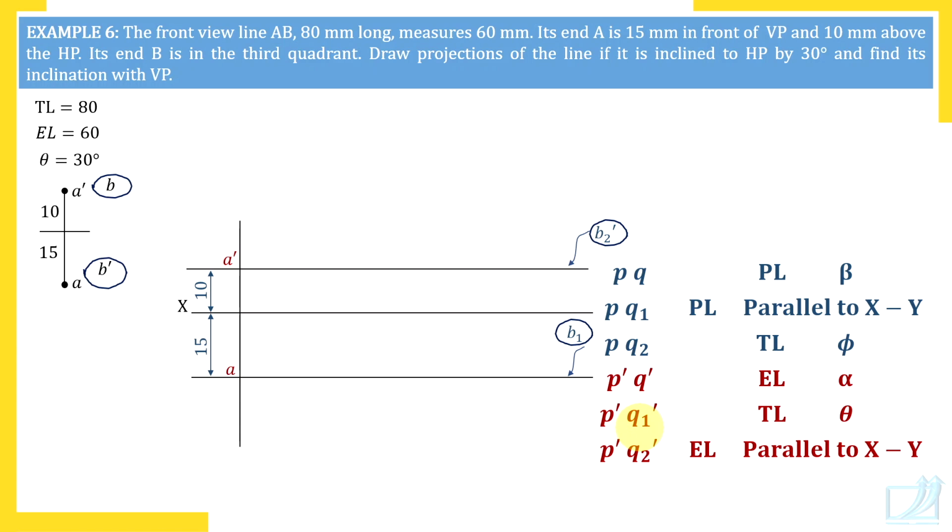Now what is the procedure? Using this 6 views logic, bring those all 5 measurements on paper. And out of 6 views, the views which you will be able to draw, you should complete by measurement only. Of course, finally, by proper construction, you will have all 6 views in your drawing. But using data, the views which you will be able to draw, you try to draw first. So check what is that data.